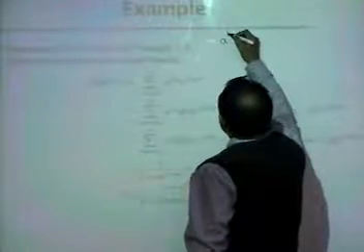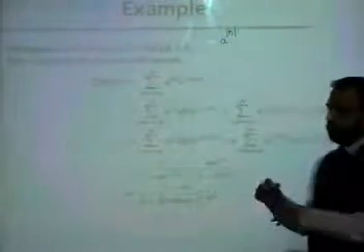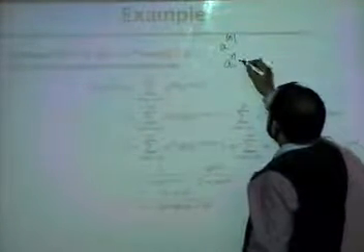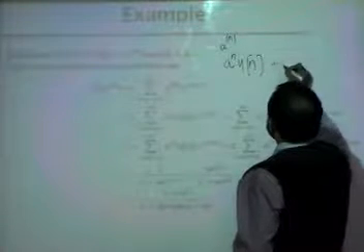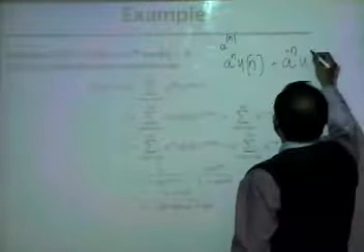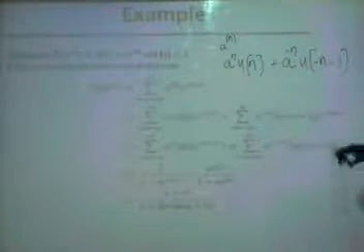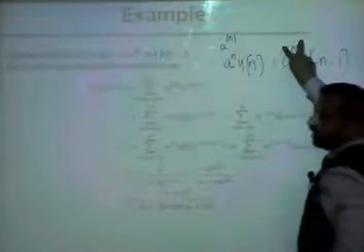So this brings us to a few examples of the Fourier transform, and this is again the theoretical part of the chapter, where you need to learn how to apply the formula and feel comfortable with this. So for example, this is a function a to the power magnitude n. So it runs for negative values as well as for positive values. So you can break it down into two parts. It is a^n u[n] plus a^(-n) u[-n-1]. It is this part with negative, because once you take the modulus of this, for negative n, it will be positive.